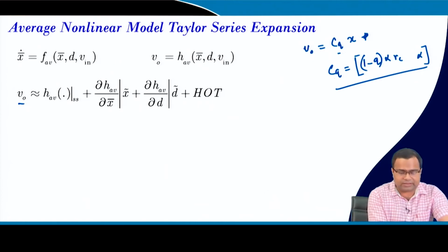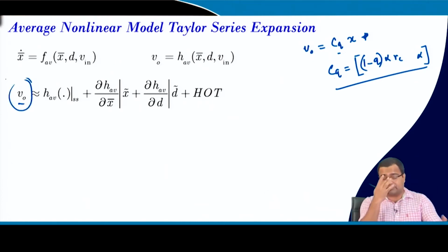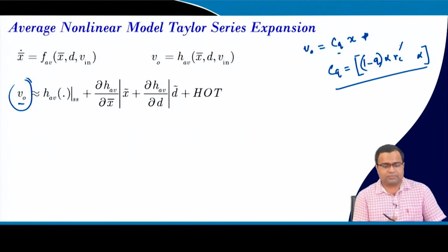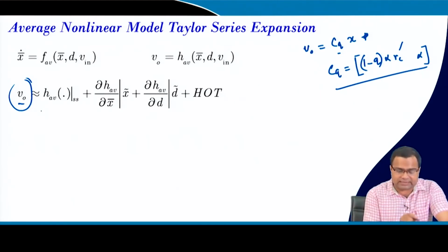So, this function can also be different, and that's why in a boost converter, when you consider ESR, due to the ESR there will be a discrete jump in the output voltage at every switching instant, and this discontinuity is coming due to the switching event. So, then we can again write the Taylor series, but here we are talking about the average quantity.